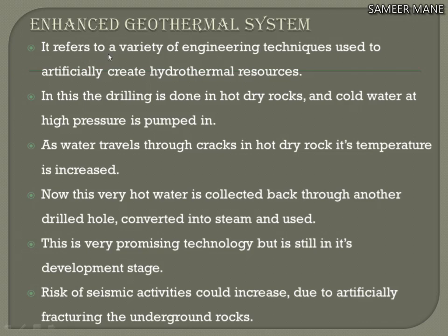It refers to a variety of engineering techniques used to artificially create hydrothermal resources. In this, drilling is done in hot dry rocks and cold water at high pressure is pumped in. As water travels through cracks in the hot dry rocks, its temperature is increased.